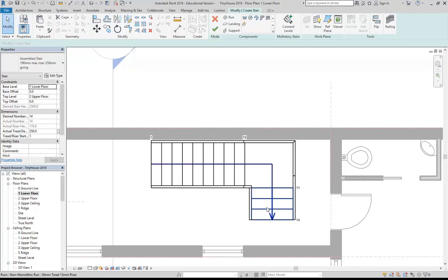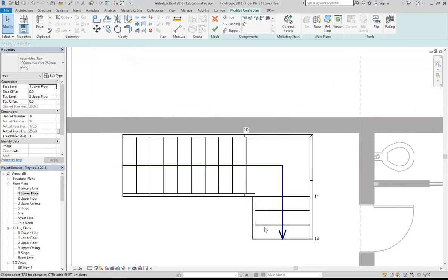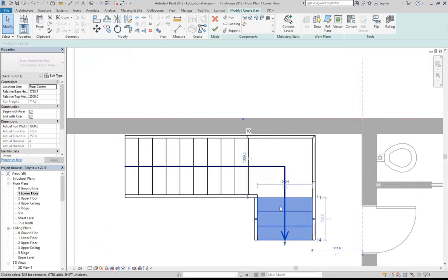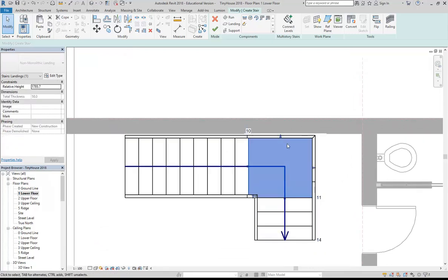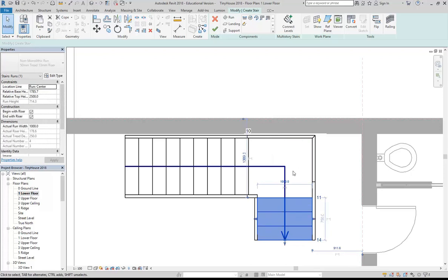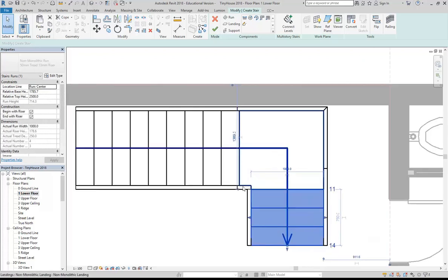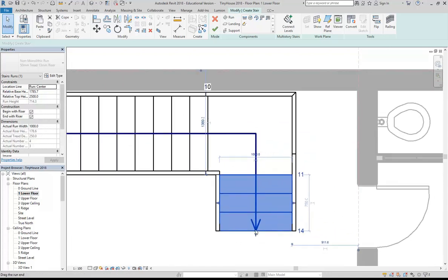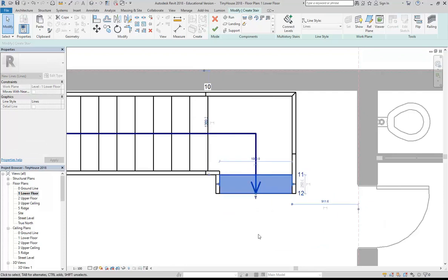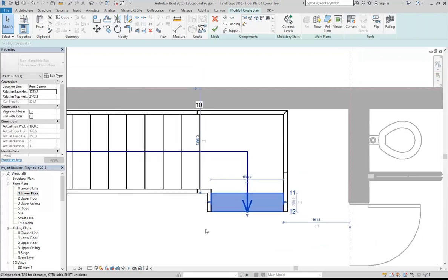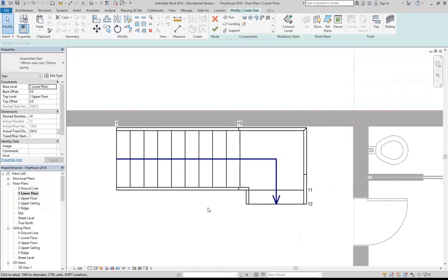And so now, oh yes, I want to put the winders in. To do that, we need to convert the stair. Also, we need to convert the whole landing actually. So say I want to put in 2 more risers. What I'll do is use the circle there to drag this back so that I've only got 1 step here. Okay, so I know that I need 2 more risers, but if someone else was to come and look at this, they would still be able to tell, even though they haven't made it, that they need 2 more.